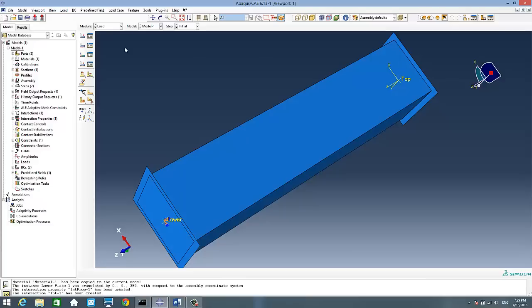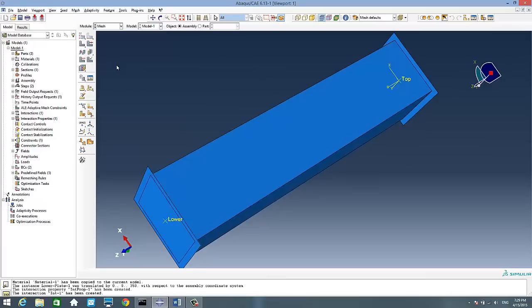We could have done the speed boundary condition from the boundary condition manager over here, but this would not ensure that the plate will leave the tube after the crash is done. Now, after we are done with the load module, we move to the mesh module.